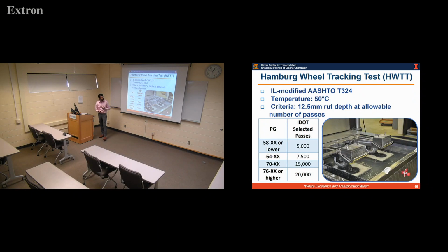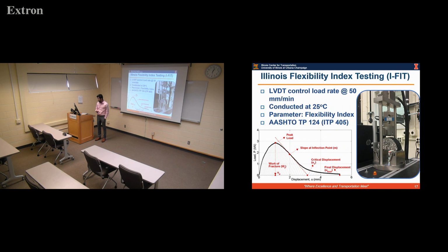In order to incorporate the rutting susceptibility, we did a Hamburg wheel track test, and to investigate the cracking issues, we looked into the IFIT test, which was developed here at ICT, as Jose mentioned.